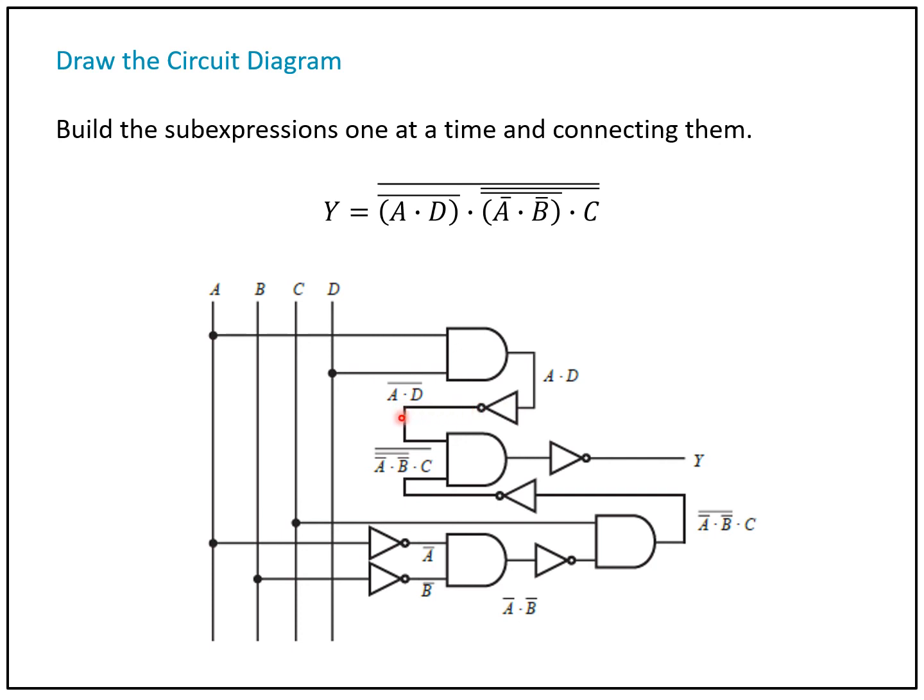Let's stop here, then move to the other sub-expression. You start by inverting A and B, as you can see. We're drawing from A, inverting it, and drawing from B and inverting it. Then you apply the AND logic here. Then notice that you need to invert the result of this sub-expression as represented here.